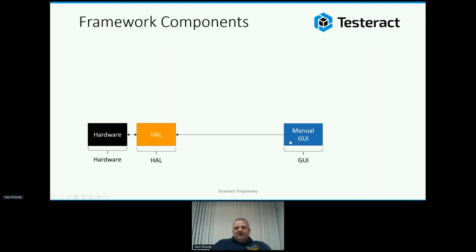You could have a manual GUI that runs a spurious emissions test or a current draw test or whatever kind of test. And so you can talk to your unit under test, your power supply, your power meter, your spectrum analyzer, and those can all be underneath a single GUI, or you can have different GUIs for each. The point is these GUIs are something that designers would use, or more low-level technicians would use to debug, to characterize, to play around with, get more intimate with the hardware than you would in an automated environment.